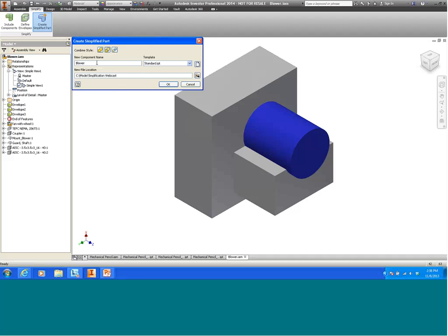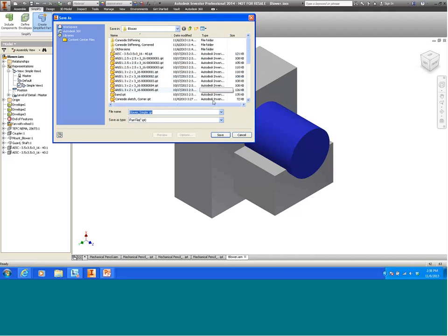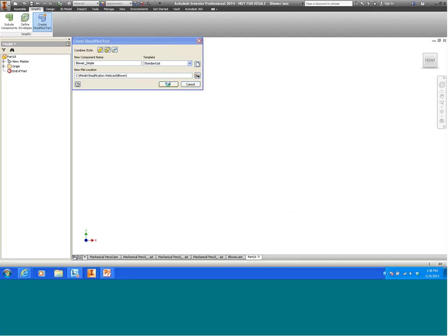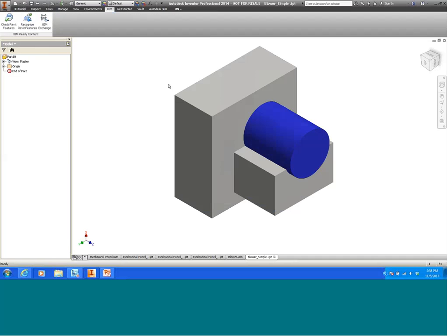One thing that's just a little tricky here, and I'll just mention, is it doesn't actually append any information here. So unlike Shrinkwrap that appended to the name, you actually have to go in and type something in if you wanted to have another name other than what the assembly was. And then the same thing holds. It doesn't maintain the directory from which you opened the assembly. So you also want to verify that you're actually using the right directory. And then I can select OK. And you can see that my model opens.